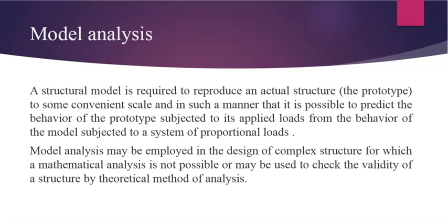There are two types of model study, which are direct model study and indirect model study. All the models, whether direct or indirect, should be designed according to a certain principle called the law of similitude, which establishes the relationship between the response of the model and the prototype. The principle of similitude is ensured through the scale factor, the factor by which any quantity in the model should be multiplied to get the quantity in the prototype. The scale factor can be determined by two methods, dimensional analysis and direct approach.